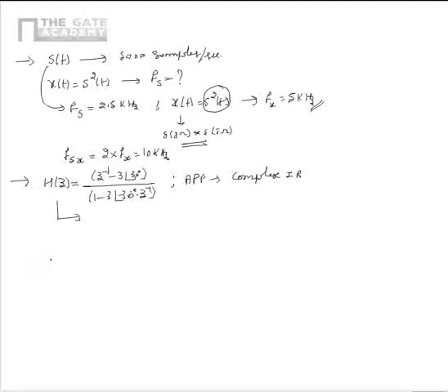It is required that the given filter needs to be made an all pass filter with real impulse response, for which we need to connect another system in cascade with H(z). We need to find the system function of G(z) which needs to be connected in cascade with H(z) to get the final filter as an all pass filter with real impulse response.